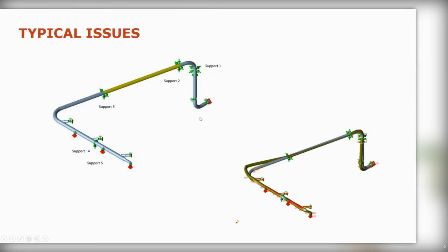The issue here was that although the pipe was only about 80 degrees, they kept failing at those Y joints where the pipe joins to the pipe. And the reason is that as the pipe heats up, this long stretch, again, it's not just about temperature, it's about how long your run is. You can always look at the system and say, this is my longest run. This is where my biggest problems will be because it will expand the most and then something needs to accommodate it.